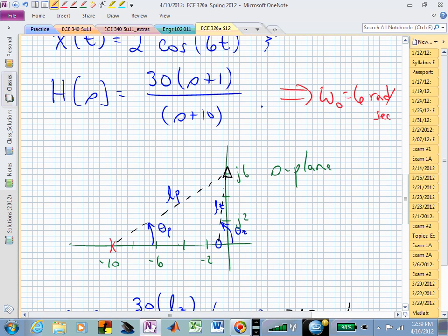And if you wanted to physically measure that, you could excite it at a frequency, wait for the transients to decay, and measure the magnitude and phase. Shake it again at a different frequency and do the same thing. Wait for the transients to decay, measure the magnitude and phase. We want to be able to do that more quickly than doing that point for point. But you could now do that if you wanted to with your calculator or with MATLAB.